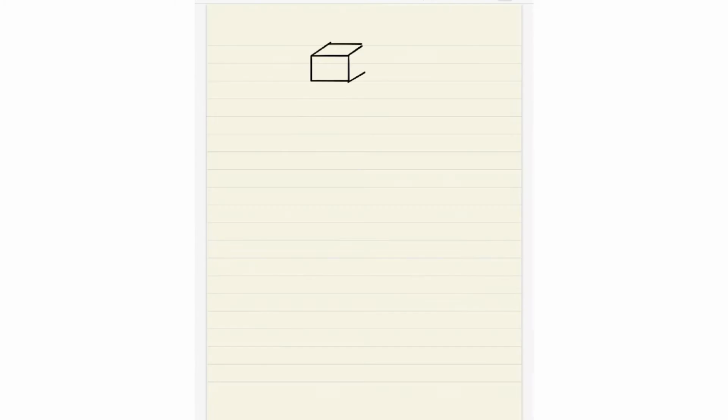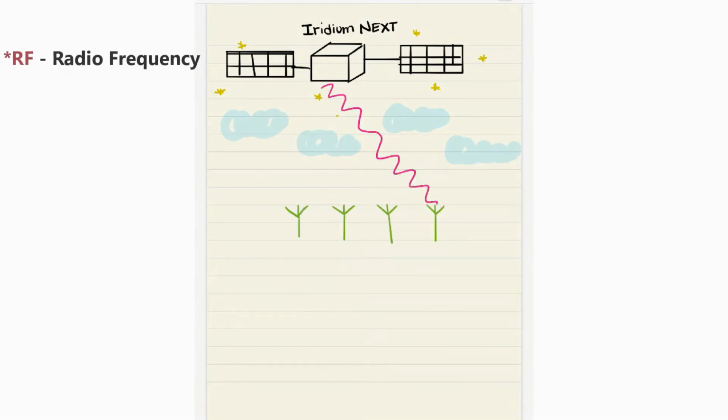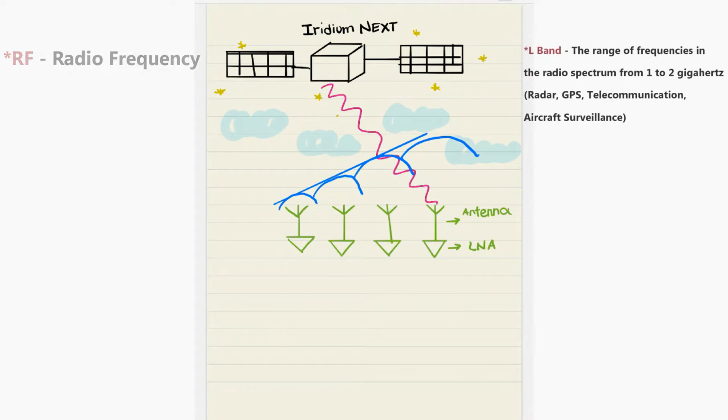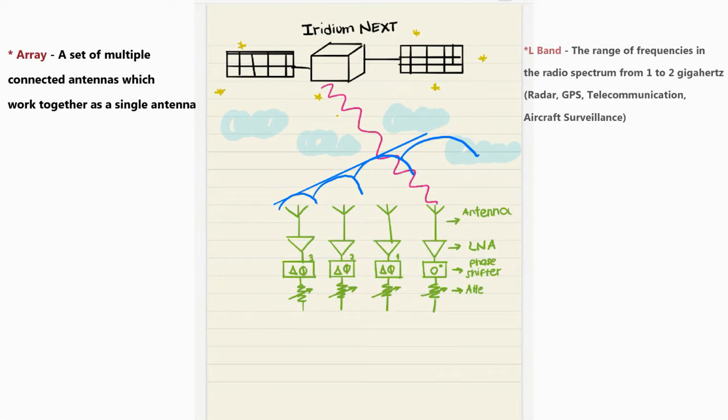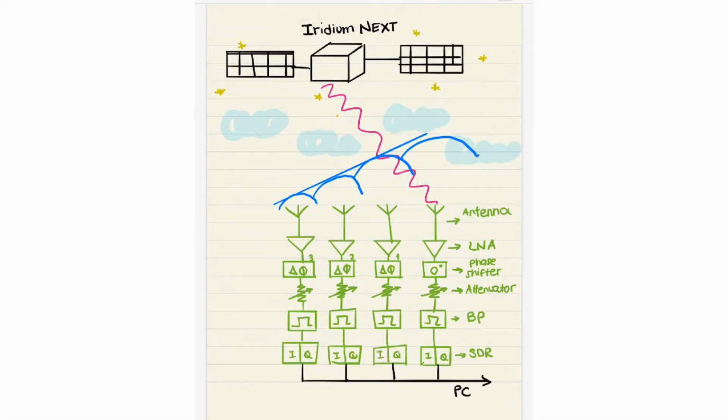To understand the basic concepts behind a phased array antenna, we will follow the path of the RF signal from the transmitter aboard the L-band satellite. The signal from the transmit antenna will travel through several mediums to our phased array ground station receiver. Due to the diversity in this space, each antenna in our antenna array receives the signal at a different phase.